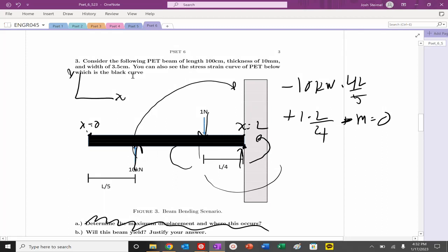We're pushing up here, so our curvature looks like this. So our curvature is positive. So what's happening with the stress right at the top? Is it compression or tension? That's actually compression, right? So we're compressed at the top and we're actually elongating at the bottom.